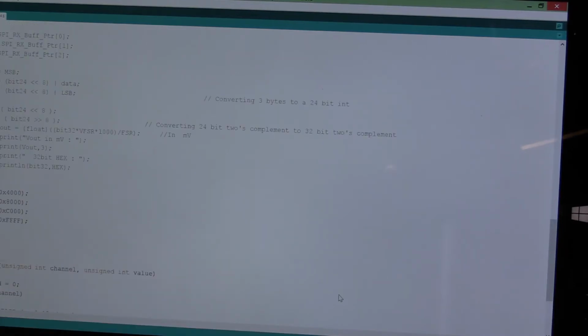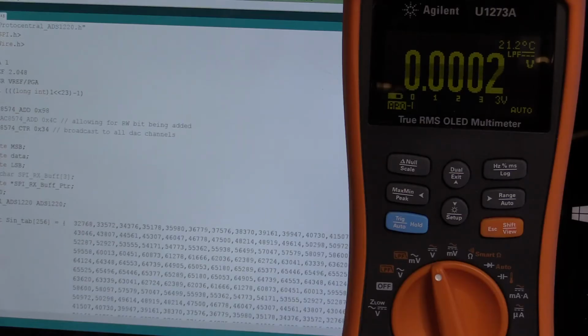All right, that's done uploading. Okay, program's now running. Everything's uploaded. So we're going to just probe the output 0. Oh, that's not 1.25. Output 1, nothing. Output 2, nothing. Well, millivolts anyway. So there's nothing on there, so we need to have a look at what's going on.